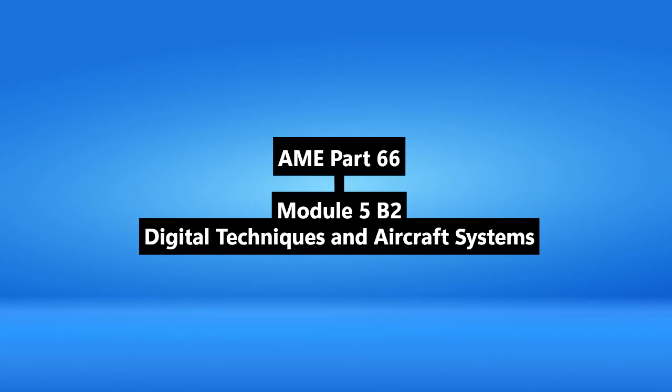Like connecting the dots, but smoothly. Sort of, yeah. The module mentions the MC1408. That's an 8-bit DAC. That 8-bit tells you the resolution, how many distinct voltage levels it can create. 2 to the power of 8, which is 256 steps. That analog output can then drive an actuator or maybe an older analog-style cockpit instrument.